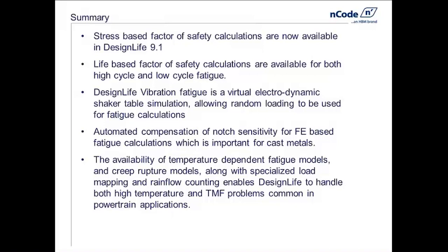We looked at using DesignLife for what we call vibration fatigue, but what that is really is using DesignLife as a virtual electro-dynamic shaker table that allows us to do random loading to do our fatigue predictions. We looked at how DesignLife uses stress gradients to do an automatic compensation for notch sensitivity. And again, this is very important as we start looking at cast metals. Many cast metals are very notch insensitive, and ignoring that can give you basically nonsensical results.